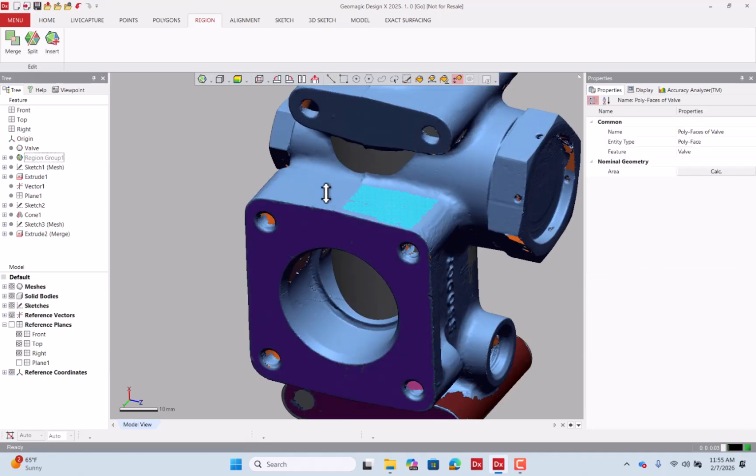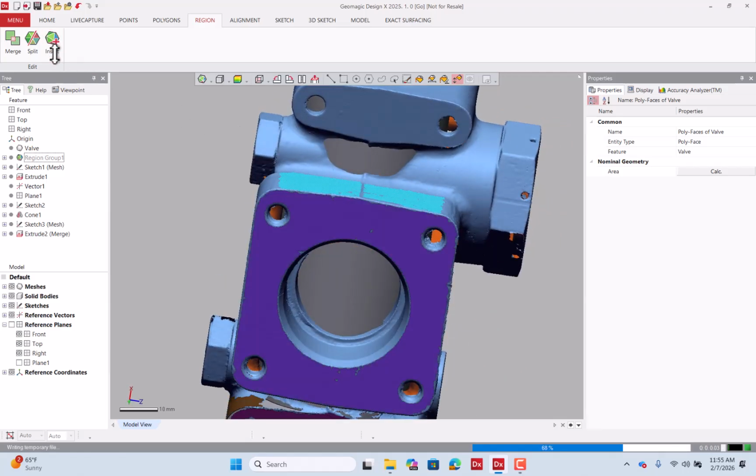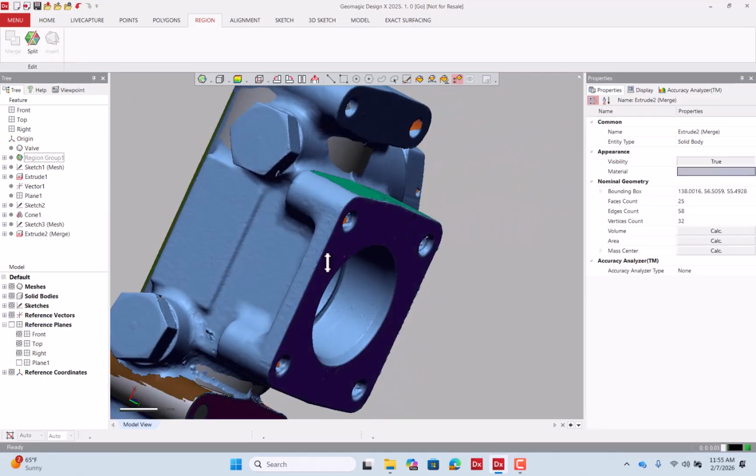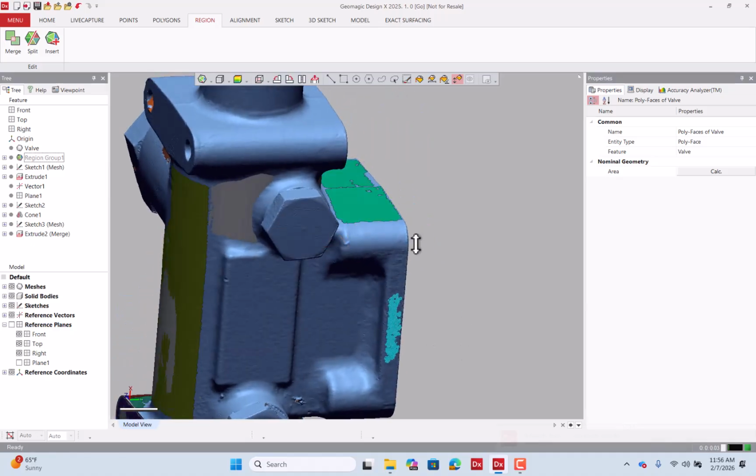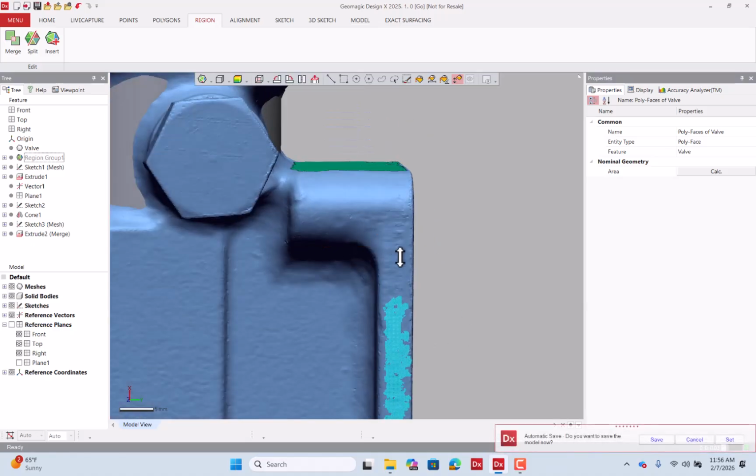Let's make further regions. This is an easy process. Just select the polygons you need, insert, and say okay. If you select excess, then you would have to separate them again, so it's easier to be a bit more careful at the selection stage itself.